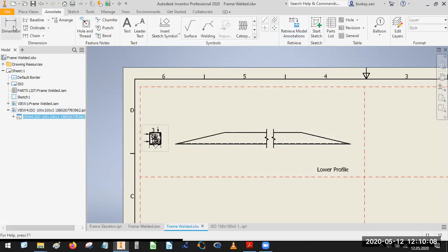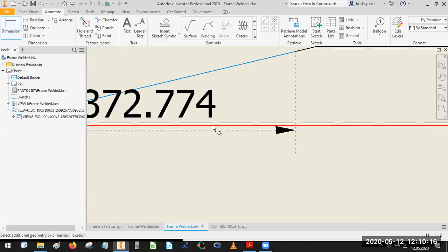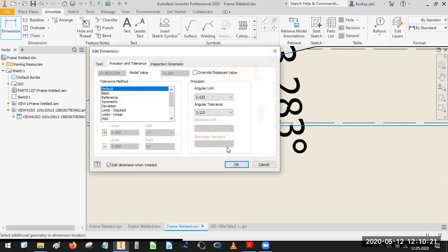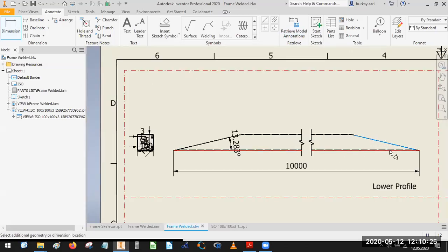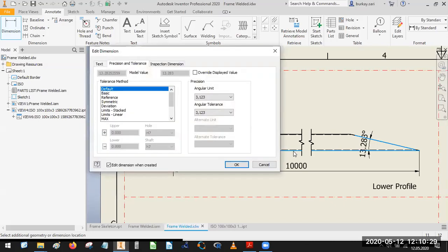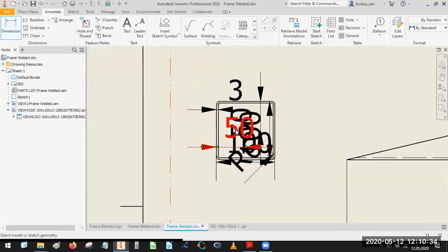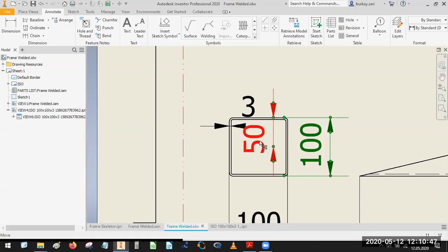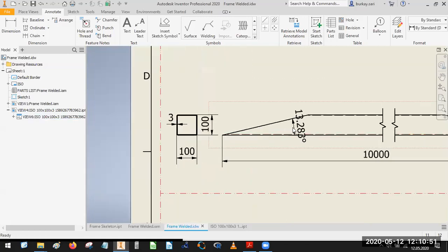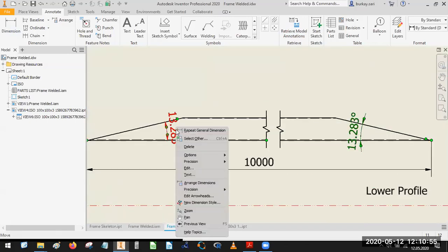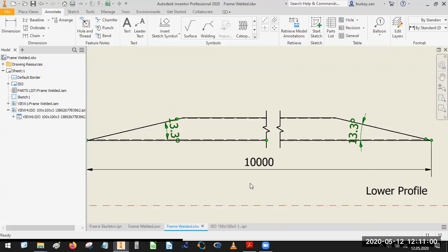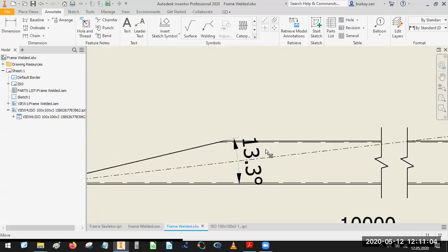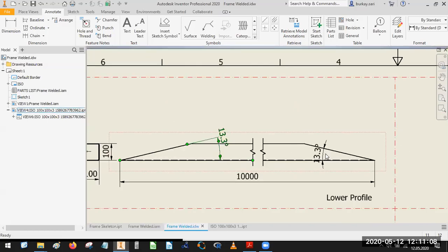Here we have. Next, we have a profile length, done manually. Also, we have to create the angles at the end of our figure. For such a big production, I'm sorry, I will just delete some dimensions because they're not very important for the manufacturer. The profile and the profile thickness must be shown here. Also, for the manufacturer, the precision after the 3 digits after the decimal marker is not of interest because it's a rough process.